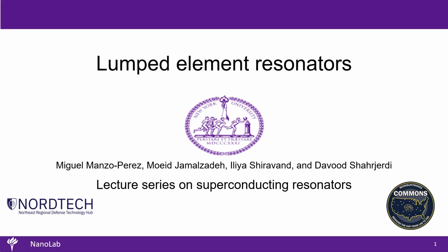In this presentation, we continue our analysis of lumped element resonant circuits. In particular, we'll focus on deriving compact expressions for the magnitude of the input impedance, which we'll later use to connect their behavior to transmission line resonators. We'll also look at two key metrics for evaluating resonator performance: the quality factor and the fractional bandwidth.